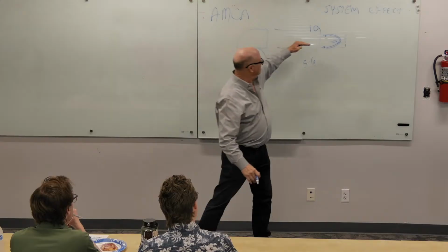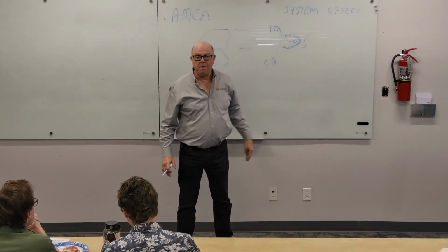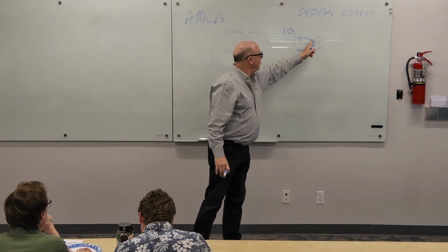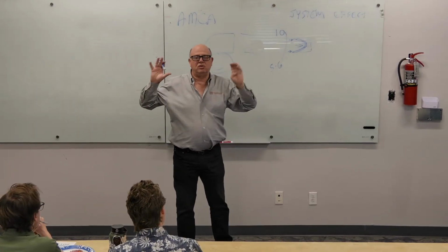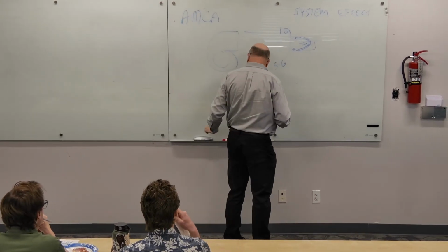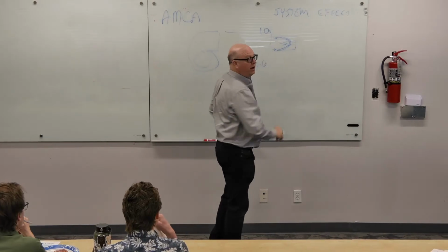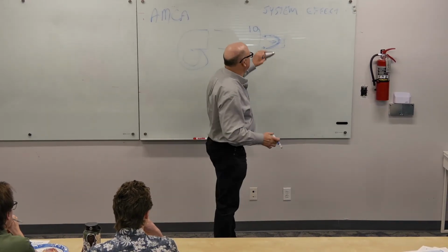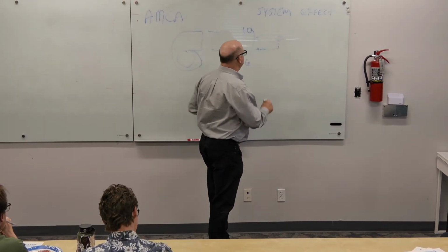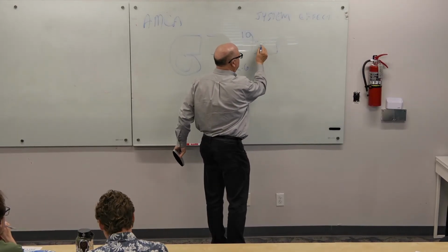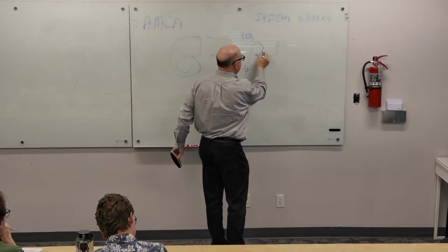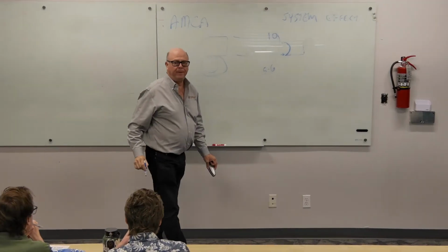Because it's coming at a faster rate. But it gets as close to being smooth as it's going to be after 10 diameters. And that's the basis of the theory of why you pick 10 duct diameters. And I may have been a little extreme. It may not be quite so bad. Maybe it's like this after 10.